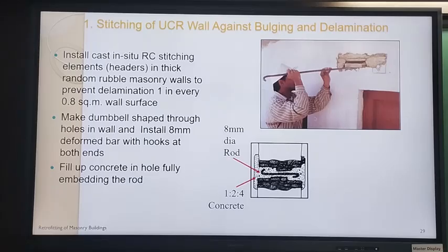And when we went to Uttarakhand for the first time, Rupal, myself, a couple of engineers, we went and ourselves worked on one wall which was part of a ruin, just to understand how to remove the stone. So it's not something extremely difficult, but you have to do it so that you don't damage it. And basically once this is filled, it's cured properly. And we have done testing on it, and it works beautifully. Our shock table test showed that this was very, very effective.